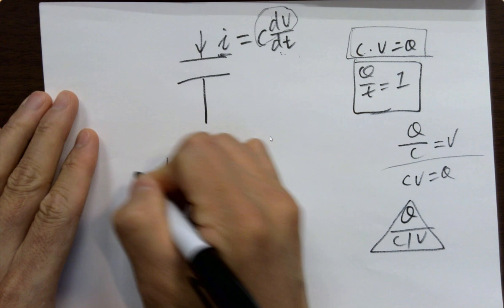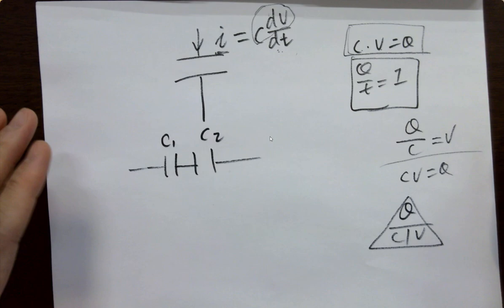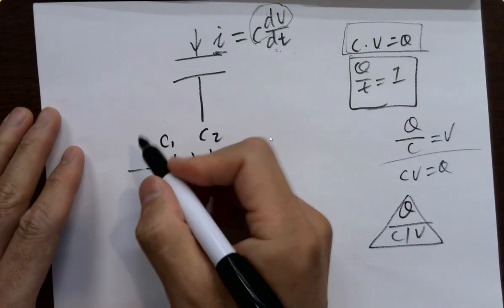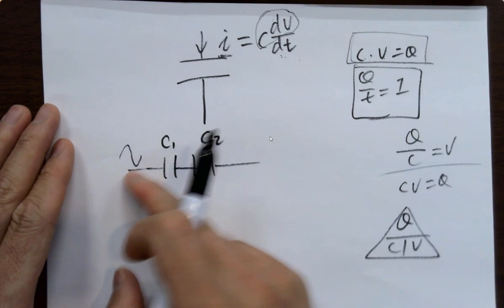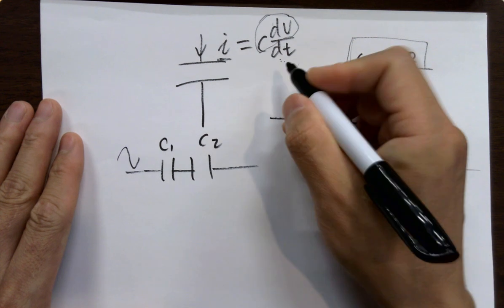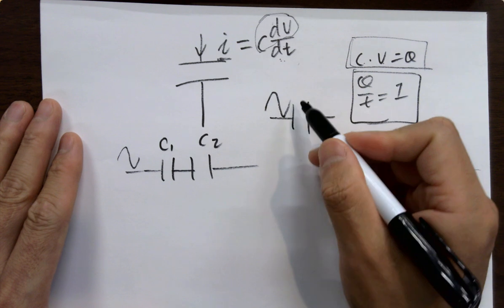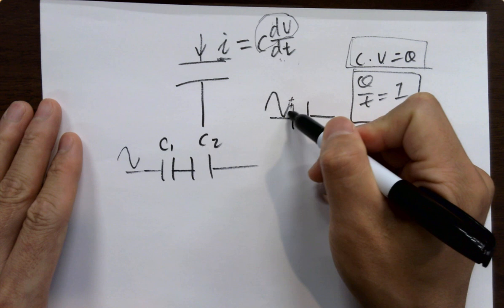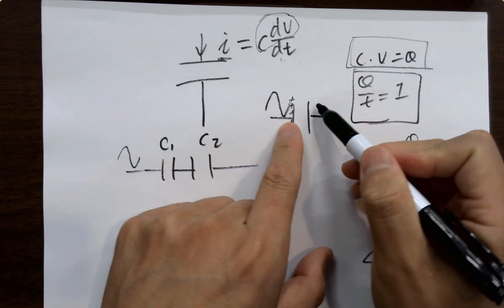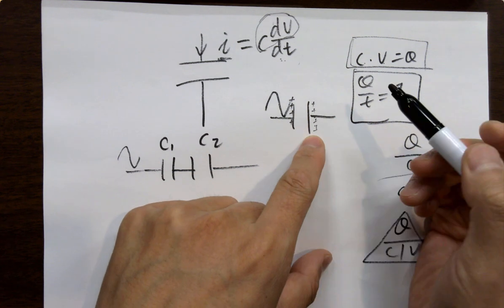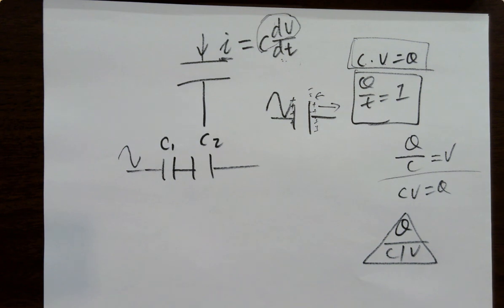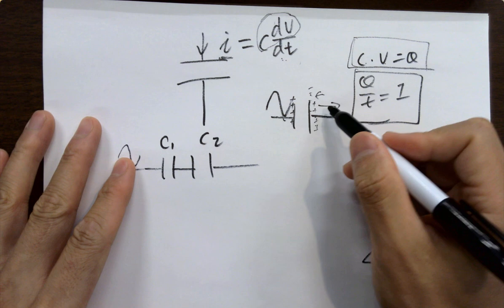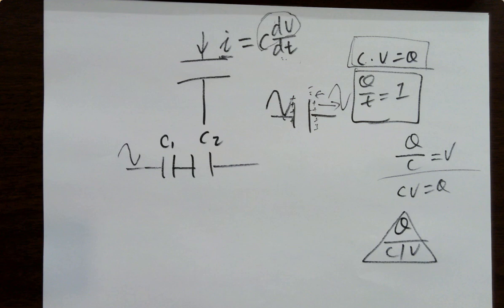So you have a series capacitor, C1, C2, and I covered this on Monday. I told you that a sine wave is able to pass a capacitor. It's a short circuit. It's like a wire for alternating signal. Why? It's because it's repelling it, right? Even though there's no physical connection. But whenever you have a voltage here, it's sending charges to one of the plates. And because the charges are accumulating here, it's repelling the same amount of positive charges away from the other plate. Or you can say it's attracting negative charges to it. It's the same thing, okay? It's repelling it away. So when you have this kind of pattern being injected into the plate, it's also repelling the same pattern there. So you are seeing the same signal exactly on the two sides of the cap. That's why we treat it as a short circuit for alternating voltages or signals.